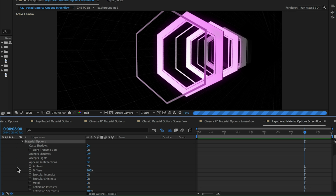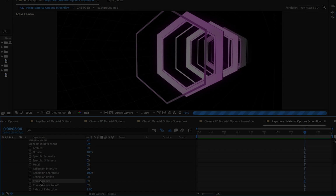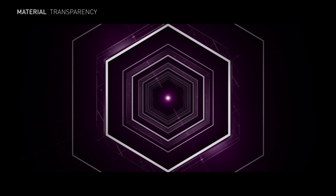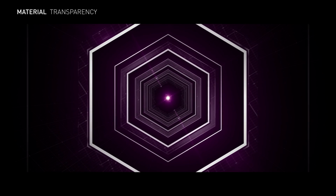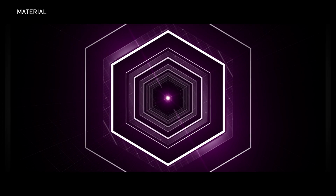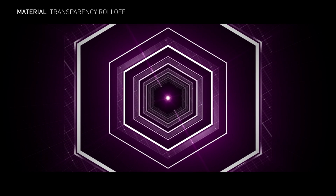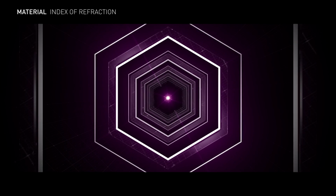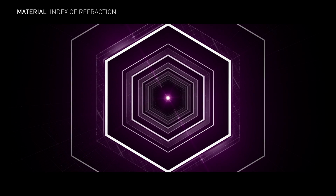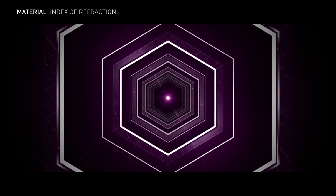Material options for the ray trace renderer are the same as the Cinema 4D renderer, with 2 added options: transparency and environment layer options. Transparency controls the material's transparency. Surfaces can be fully transparent, but still show reflections and specular highlights, like seen in glass. Transparency roll-off controls the amount of transparency relative to the viewing angle on a transparent surface. And index of refraction controls how light bends and distorts through 3D layers, with a value of 1 equaling no distortion and a value of 5 equaling solid glass or water.